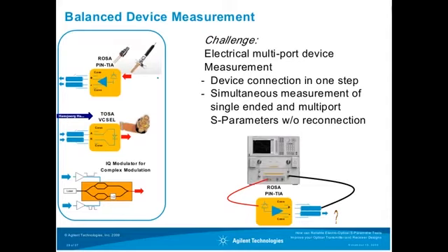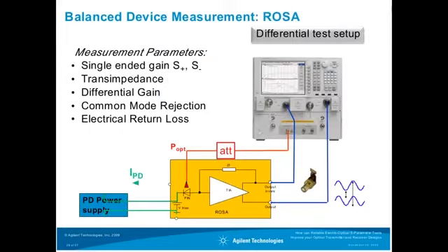For the complex modulation, very advanced modulators are also operated in push-pull operation, essentially to reduce the overall drive level, but also to impose both I and Q modulation for QPSK signals, for instance. Now, such a configuration for differential components is realized by multi-port electrical network analyzers.